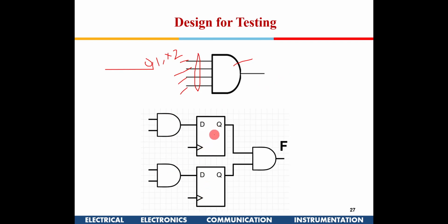This we learnt a little bit during our VLSI days, when we capture the output through flops in between, right? So that is the reason most of the gates are restricted to 2 inputs itself, because you now have to cater for x and z also. So many input combinations are there.